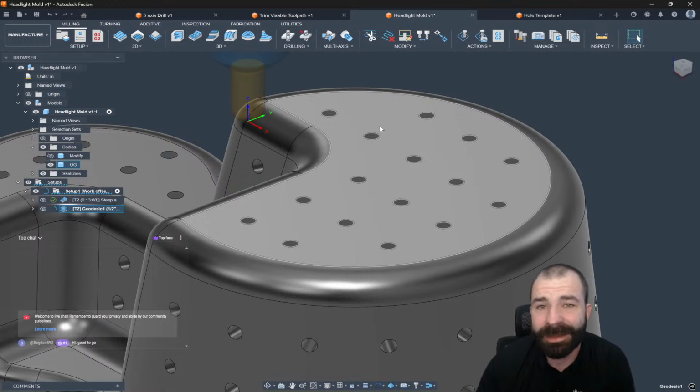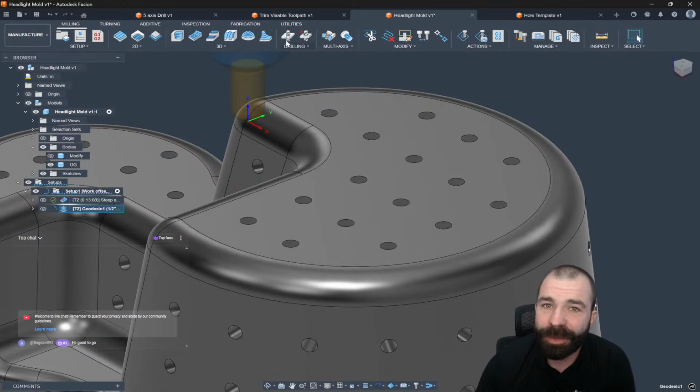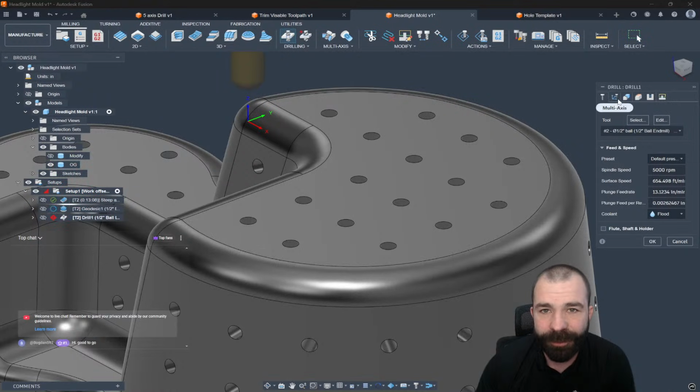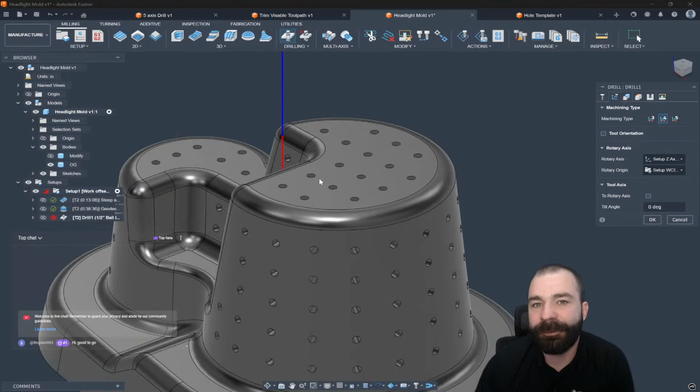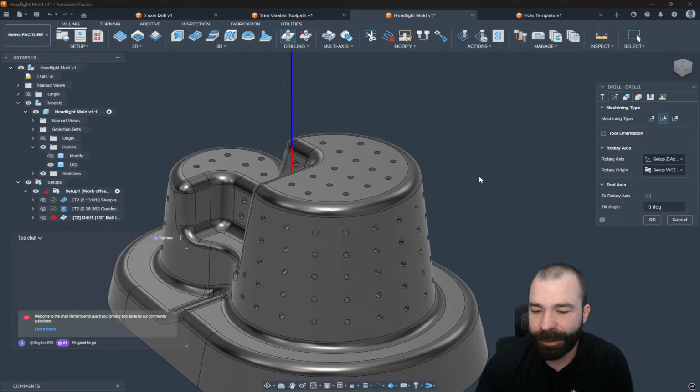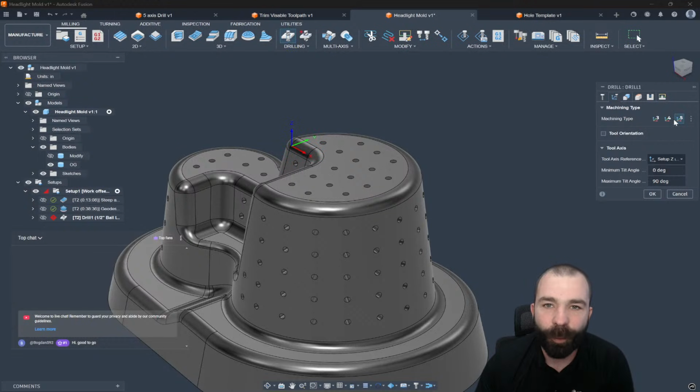So as you're seeing, again, we're getting that calculation, but I'm going to shift gears here real quick, and I'm going to jump down to the idea of multi-axis drilling. Now, it is referring to multi-axis drilling. However, it is positional drilling, right? So with that being said, you have your 4-axis ability, if you guys aren't familiar with the rotary setup and ability, and then we can go full 5-axis.